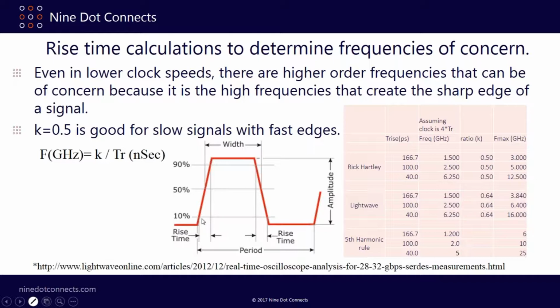A rise time is typically defined to be between 10 and 90% of the entire change in voltage. It's called an 80% rule. So that's the time that I've got over here in this table. That's the time when you're going to be looking in your data sheet to try to determine what rise time they're talking about. That's the 80% rule.